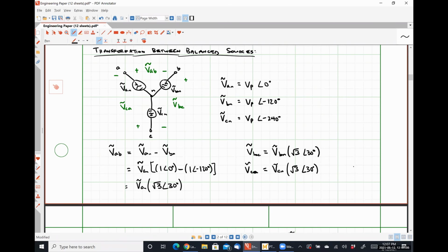That's the method I was thinking. I just forgot about the word so voltage. So we defined it by using Kirchhoff's voltage law, but now that it's defined, we really don't ever have to do that KVL equation again, right? So if we want to go from the line voltages to the phase voltage, and specifically we're looking at the magnitudes here because that's all we were given, we just need to divide that voltage value by the square root of 3, okay?